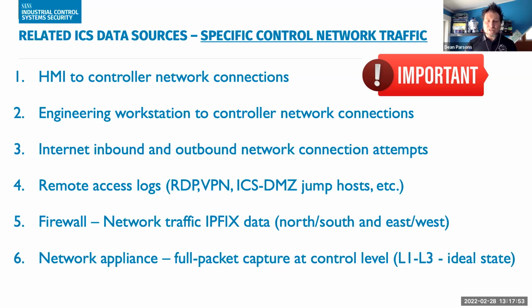And this communication on the network will allow you to understand which engineering workstations are purposely authorized to communicate to the PLCs. And if you do see that communication outside of what you expect, outside of an engineering approved change window, then potential malicious activity could be afoot.